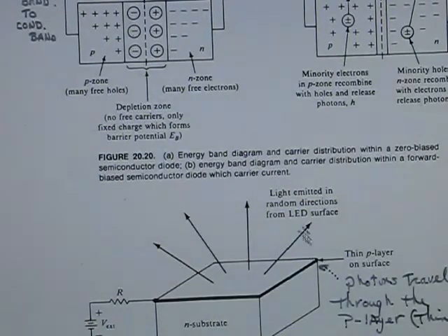So unlike a laser, it has to be focused by some external means, and there have been advances in diodes that do that. Now the reason that the P-type layer is so thin is the photons are actually generated at the junction when electrons are forced across the junction by the forward bias, and when they recombine is when a photon is emitted.